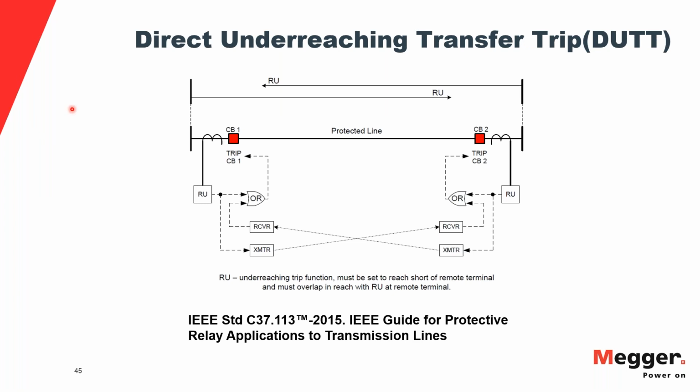Now, in the case of direct under-reaching transfer trip, well, the name says it all. It's direct trip, which means that as long as one of the relays sees the fault, it trips, and then it commands the other guy to do the same. Under-reaching, because they're only looking for faults on the first zone of protection.